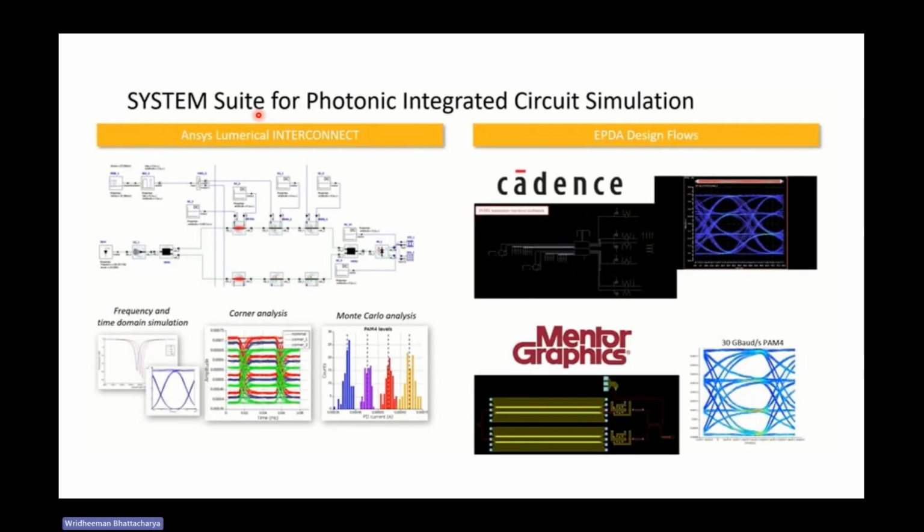So this is the system suite for the PIC simulation. Basically, we could do the device part on our own in FDTD, MODE, and CHARGE and HEAT solvers. Then do it in the numerical INTERCONNECT, where we could see the frequency and time domain simulations, the eye diagrams, the corner analysis, how they are working, and the Monte Carlo analysis.